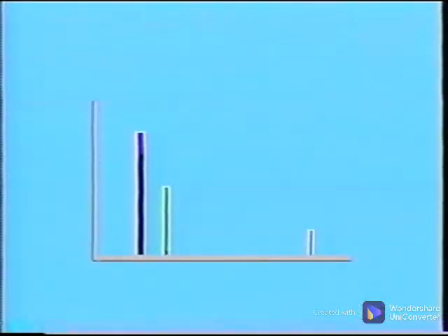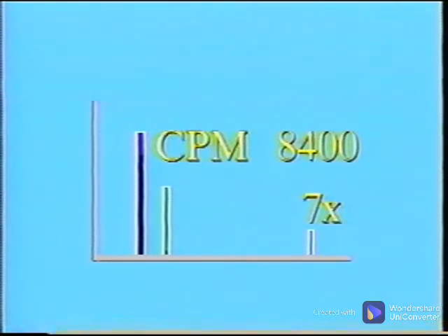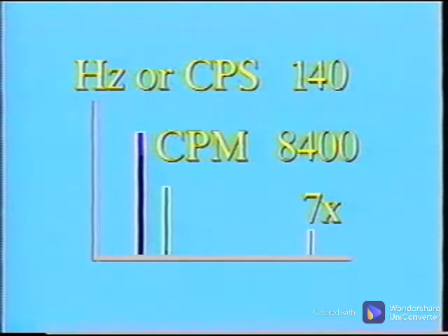This new peak represents energy that occurs 7 times during each shaft rotation, 8,400 times per minute, or 140 times per second. It is common for machinery to generate many frequencies that create a very complex waveform, and thus many peaks in the spectrum. Determining the source of the peaks and the severity of the problem is the challenge for the analyst.